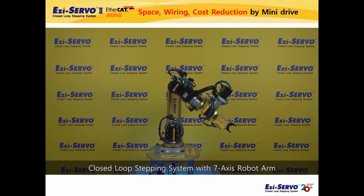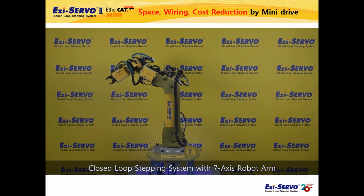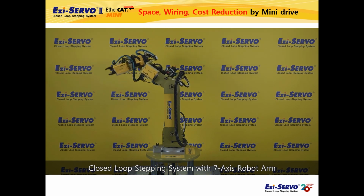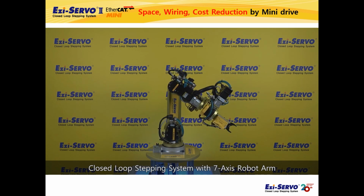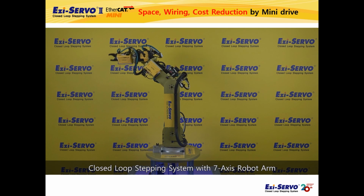The actual wiring is only one EtherCAT communication line from the EtherCAT master and a 24-volt power line. In conclusion, since the cable wiring is reduced, there is a great effect of reducing the cost and preventing malfunction due to wiring.